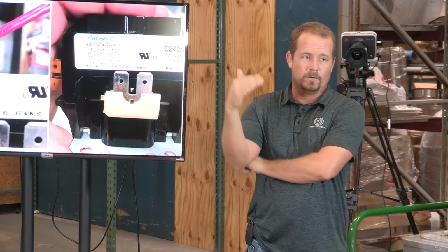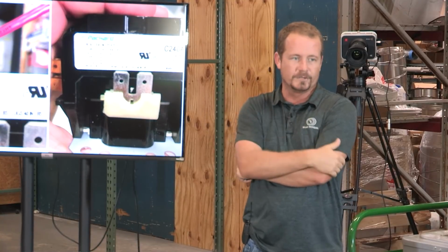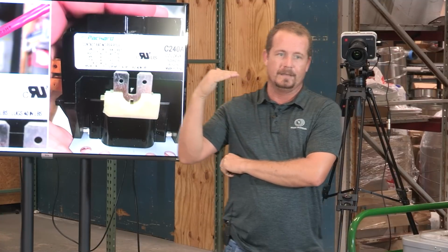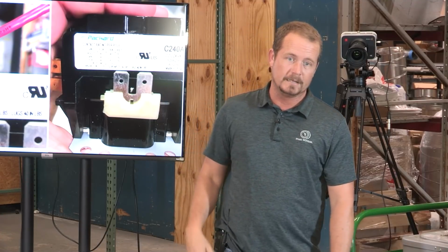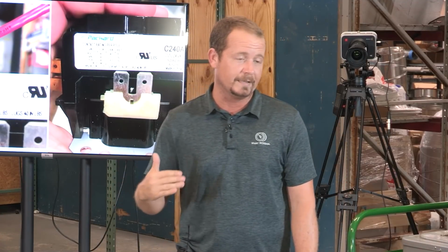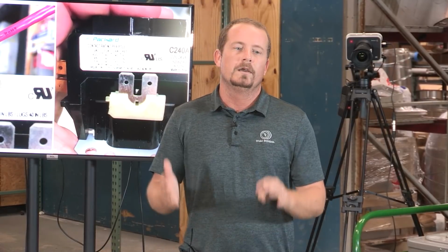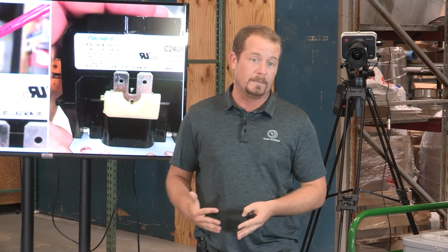We actually tested it where we created a voltage drop going into a unit and just kept dropping the voltage lower and lower, and the amperage went lower and lower until the point where the motor stalled completely, and then it went to locked rotor. But that locked rotor was a much lower locked rotor because the voltage was lower. So when you put lower voltage to something, you actually drop its current, and you also drop its capacity.